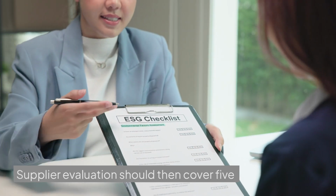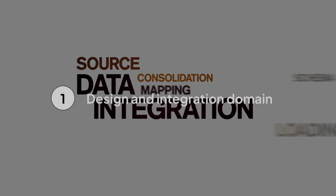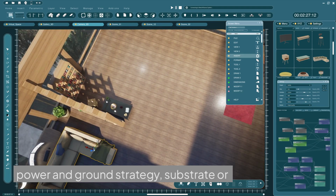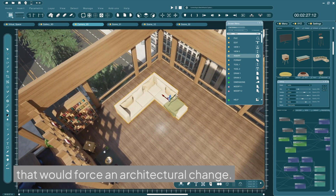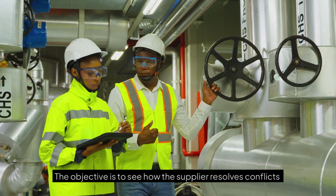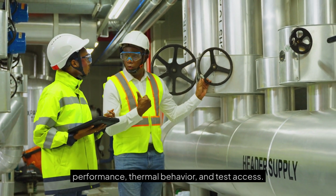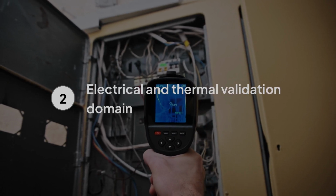Supplier evaluation should then cover 5 evidence domains. The first is design and integration. Request the required design inputs, interface assumptions, floor planning logic, power and ground strategy, substrate or interposer considerations, and the limits that would force an architectural change. The objective is to see how the supplier resolves conflicts among die compatibility, package size, electrical performance, thermal behavior, and test access.